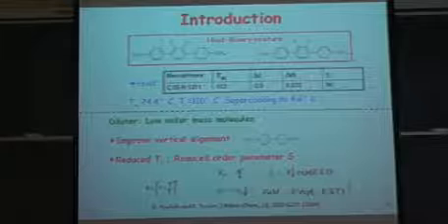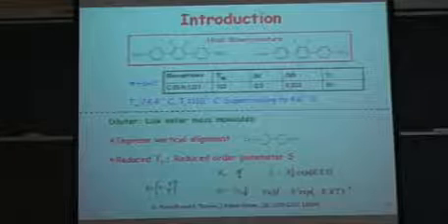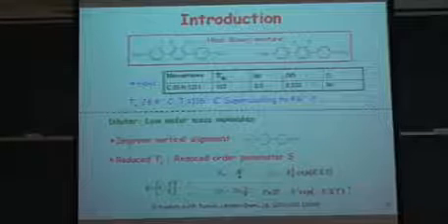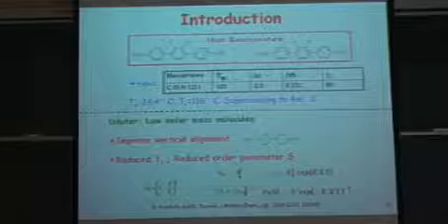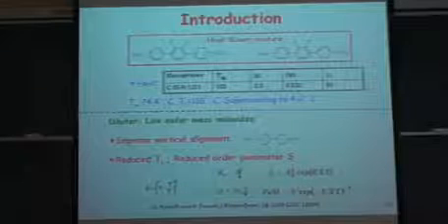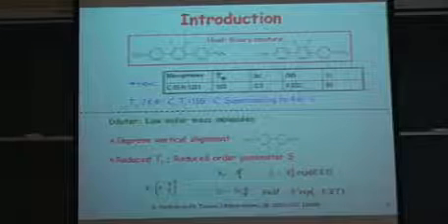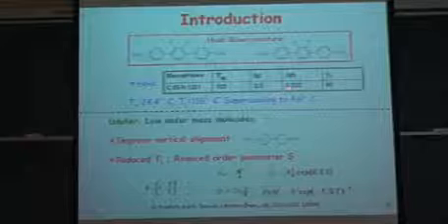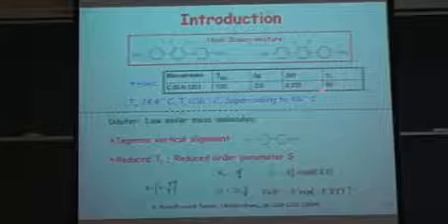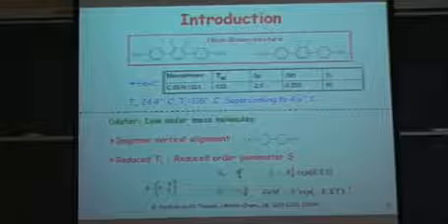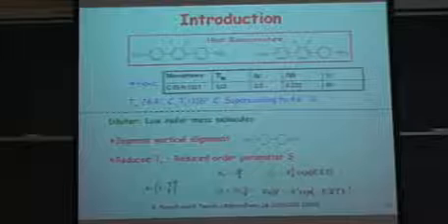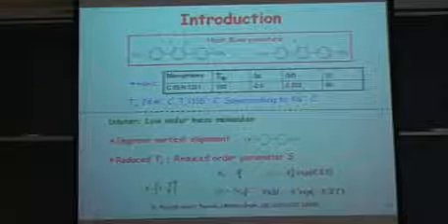It has a birefringence of 0.23. For liquid crystal display application, this is a large value. For photonic devices, the birefringence is about 0.3 or even 0.6. But for display, usually the birefringence is very low, 0.06 or something. So this is a very large value. And also this material has low viscosity. And because of the supercooling effect, at room temperature this binary host is in the liquid crystal phase.